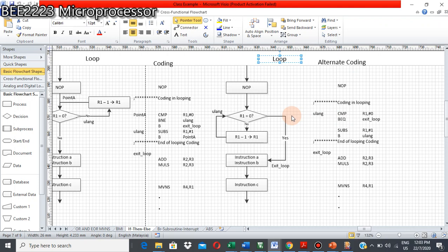If we want to generate a 1 second delay, we can modify the program so that micro-P executes this looping for 1 million times. 1 million times 1 microsecond is equal to 1 second, right?